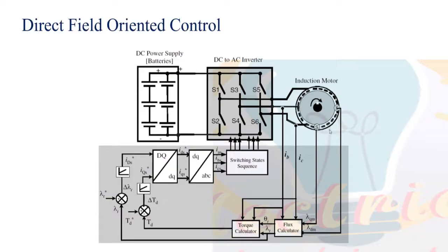If you have a controller, when the driver presses the accelerator, the controller understands this is the torque required by the driver. And now what is the controller doing? The controller goes inside the lookup table and searches for the current. But you cannot get the current very easily, like I am telling here. There are a lot of things happening behind. The controller wants to find exactly what current is required to run the motor at this particular torque. How is it determined? Let us understand that.